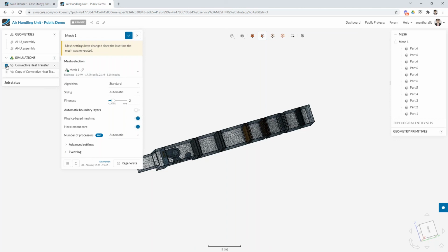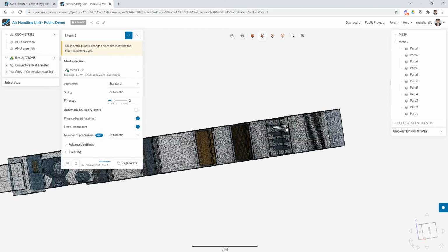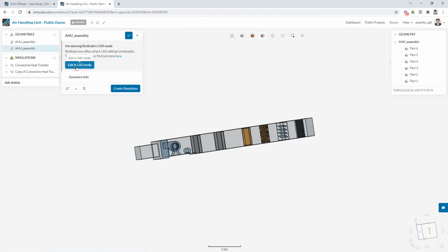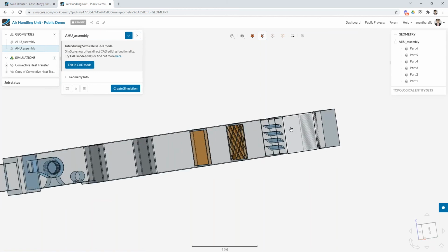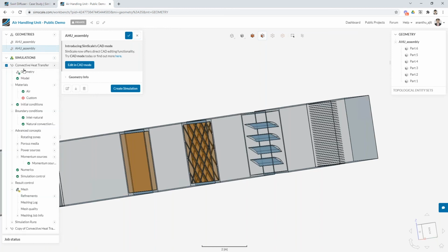That's again an interesting question. So if you have your blade angles modeled in the initial geometry, what you can do is go to edit in CAD mode, and then you do have this translate or rotate option, where if your blade is modeled separately as a volume, you can select those volumes and then change the angle of the blade, bring in a modified CAD, and then when you have the modified CAD, it's going to be simple to set up the simulation because you already have a simulation which is working, which you're confident with.